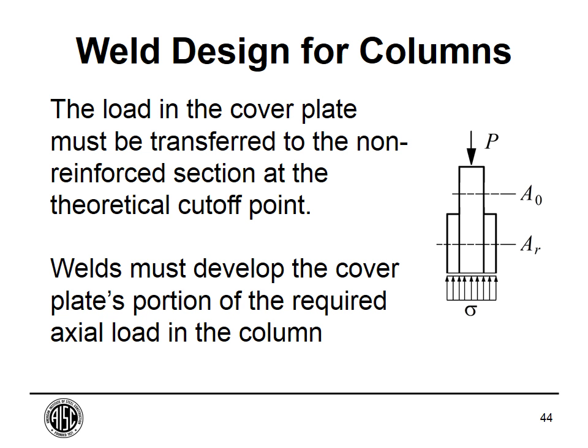Now, before we get into that shear flow stuff, which is what the questions were about, don't forget this part. This is the part that I think is the simplest. But once you get into the shear flow calculations that I'll show you in a minute, we may kind of forget this part. At the theoretical cutoff point, at the end of your reinforcement, you have to develop whatever load is in that reinforcement through the weld to get it into the original member.